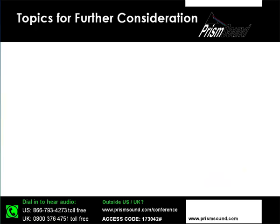A few topics for further consideration. We've made several references to the fact that we just don't have time today to talk about everything in the kind of detail that you might want to understand in order to be able to fully analyse every component of your Bluetooth audio system. And one thing that I had no time at all to talk about was what you would do to make a microphone measurement. The theory is quite similar to loudspeaker measurements, but in this case you would typically use a full head and torso simulator with a mouth simulator coupled with a reference microphone in order to quantify the performance of your headset microphone.